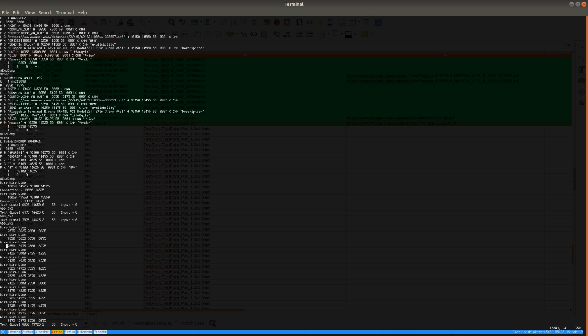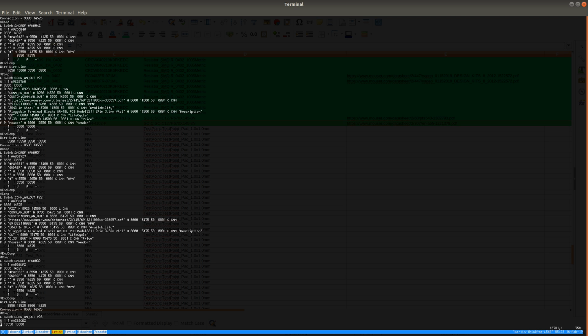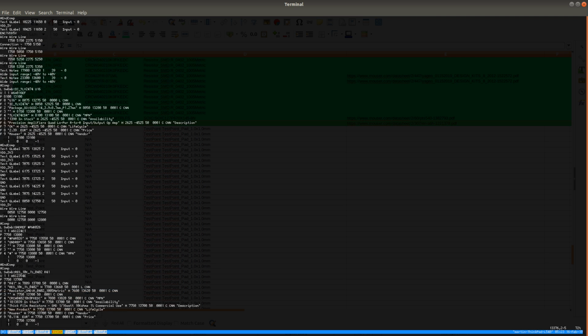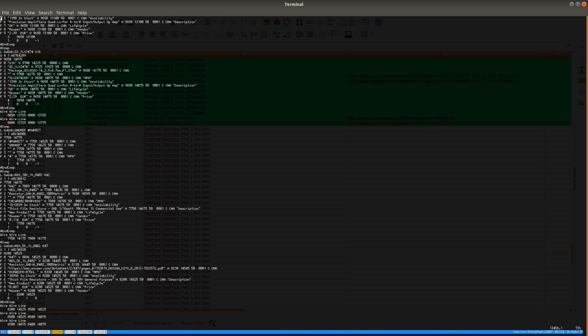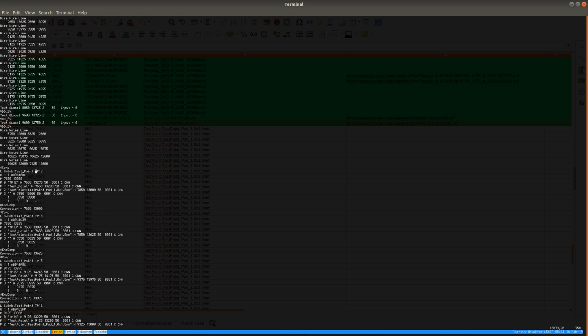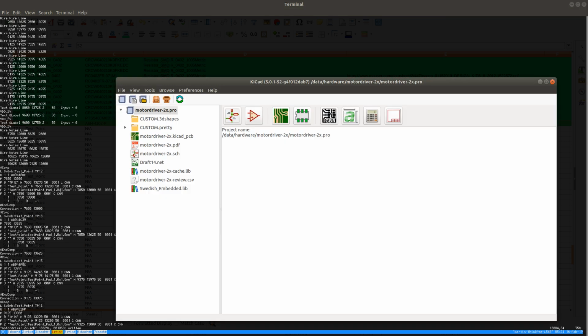Well, actually, maybe H does not mean hidden because, for example, P27 is not supposed to be hidden. Yeah, it seems that it's the L and the C. So let's see if this works. We've got TP12, and if we make this L, does this make our test point field visible?